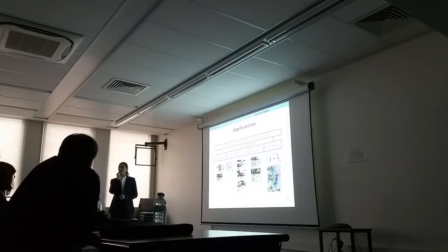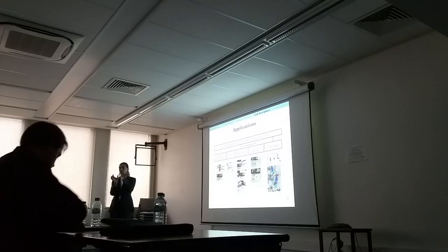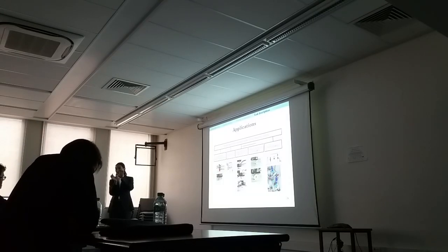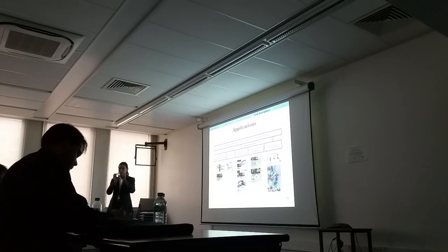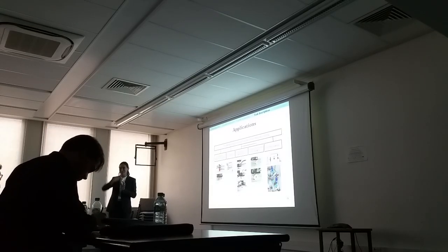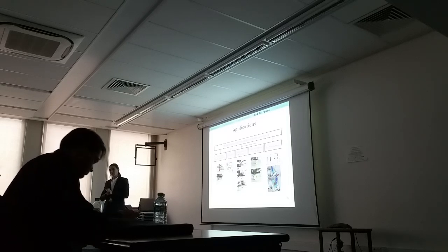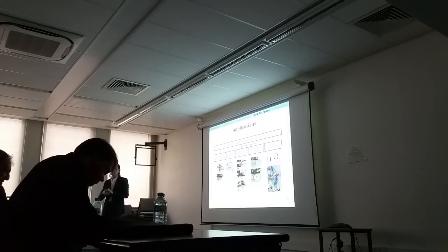I discussed it there, yes, because we can have a trajectory layer where we compute the trajectory for the convergence along the X-axis and along the Y-axis, taking into account that the sensor size is different. That's why we can tune the PI gains in order to converge the error at the same time. They do not converge at the same time. It's strange because it's a very good response in the X direction, but not a good response in the Y direction. So you think it's because of the gains? Yes, it's only because of the gains, or we can add the trajectory calculator.